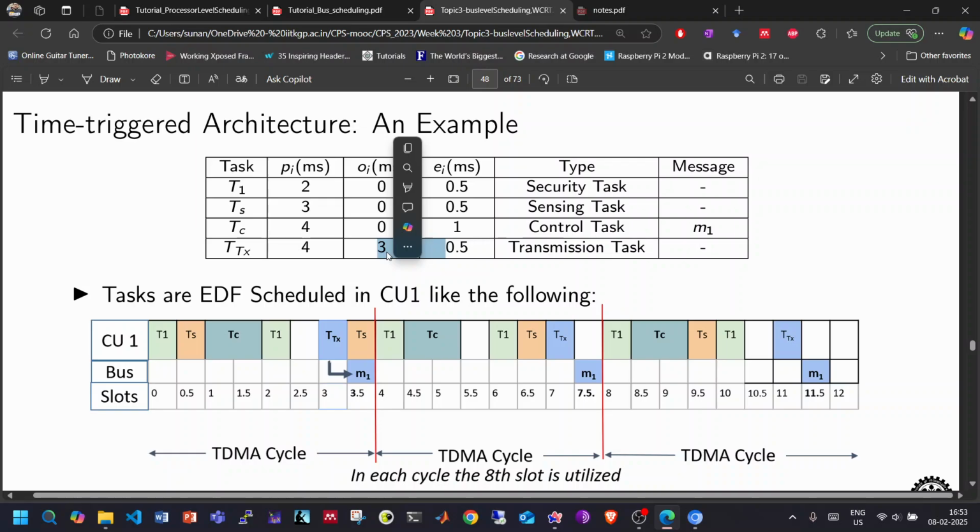How is this offset chosen? When we do critical time analysis, we consider all of the tasks will be arriving at the same time. Without any offset, this would have executed before some other task. So this offset is basically working as a precedence. Ideally, instead of precedence, if we are doing something in an asynchronous way, we use offset.